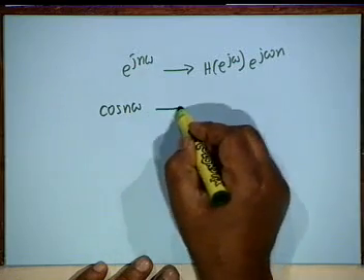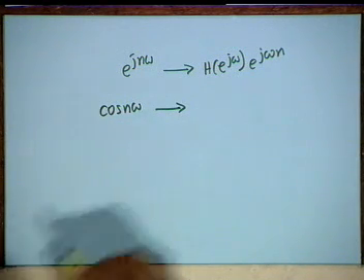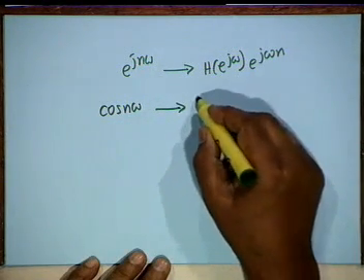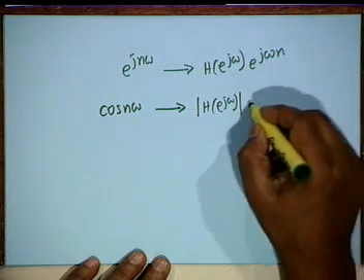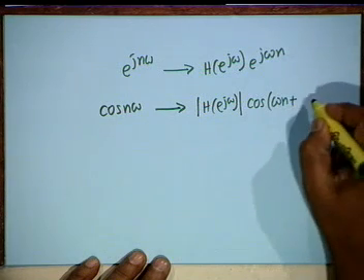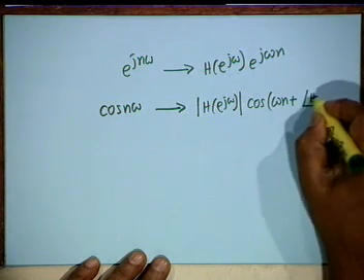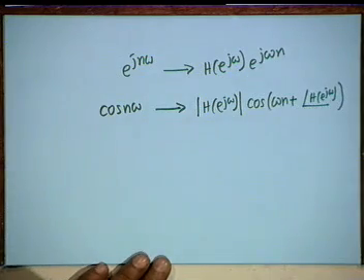In other words, cosine of n omega, if we know the response to e to the j n omega, then we know the response to cosine n omega also. It will be real part of this, which means that capital H of e to the j omega, then cosine of omega n plus angle of H of e to the j omega. Alright, that is all that it matters.